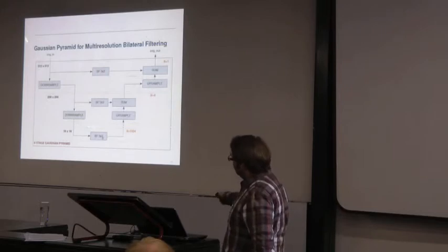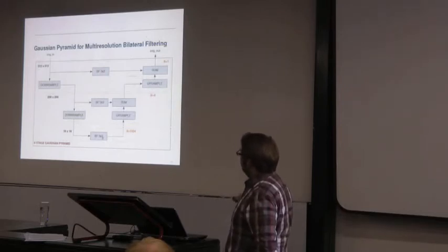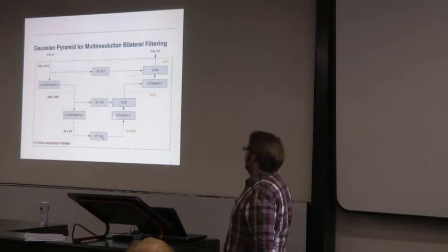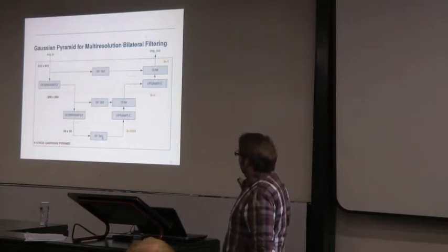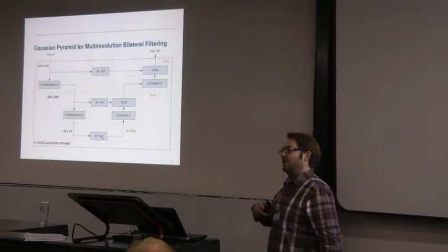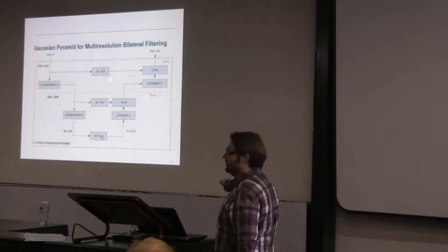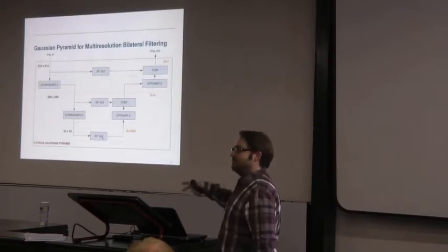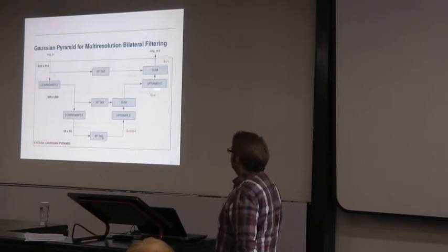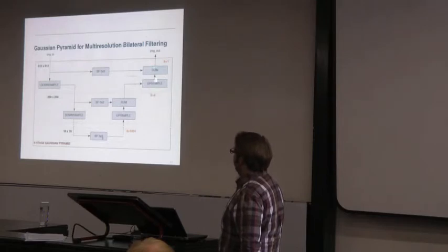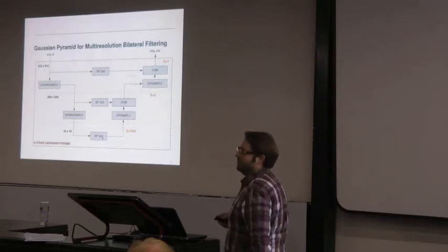Now you see the V cycle. First of all, we go down, and then we go up again, because in each and every level, we first do an upsampling, and then we combine the results from down here with the results in the current stage. So all of these are local operators, meaning you get a lot of delay, meaning you have to buffer a lot of data. Remember, this runs with an iteration interval of 1, meaning it reads 1 in every cycle, and after a certain delay, it produces 1 in every cycle. So you have to wait until everything has rippled down through here until you combine here. So you get a lot of delay here, meaning you have to do a lot of buffering.